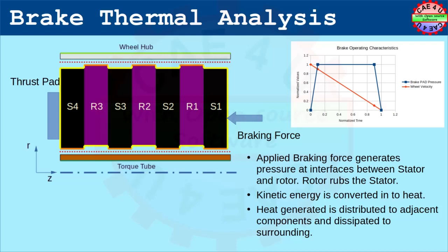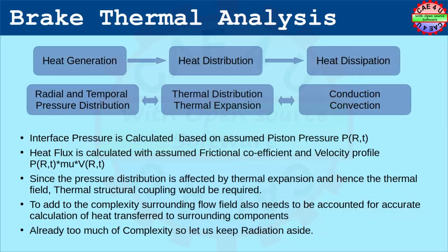The braking force is typically applied using a hydraulic piston where the hydraulic pressure is increased in a manner which exerts the braking force, resulting in a linear reduction of the velocity till the stopping distance. The entire braking process can now be split into three sub-processes where heat is generated, distributed and dissipated.